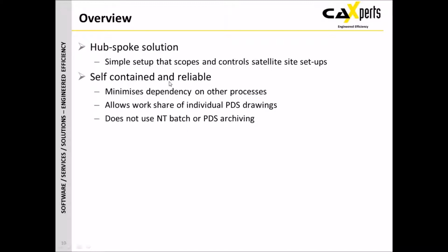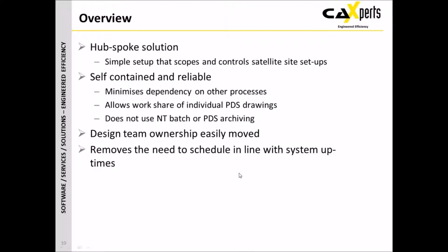It's self-contained and reliable, so it minimizes dependencies on other processes. It allows workshare of individual PDS drawings, and it doesn't use the NT batch or PDS archiving as a mechanism for working. The design team ownership is easily moved, so if you have one particular office where you want them to be in control of the equipment, another in control of the piping, this is easily done.